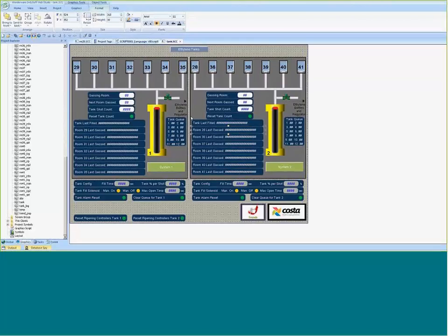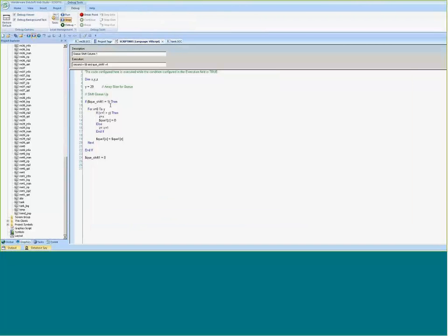delivered. And the last one was when we utilize the array functions, we use the for loop here to basically shuffle data around within those arrays. So the PLCs we used on site, they didn't really necessarily have the smarts to really sort of crank out that sort of functionality. So we just basically hid it into InduSoft, and it works exceptionally well.